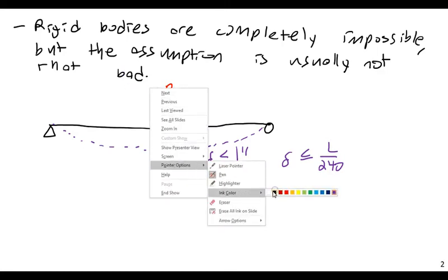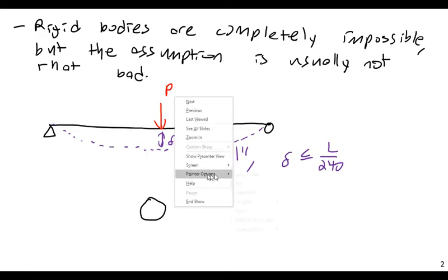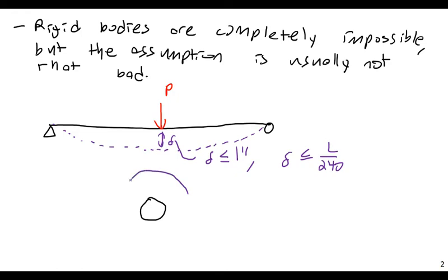It happens with moving systems. So for example, if I have a rotating shaft, a drive shaft that is rotating, the stresses within this, as you learn in mechanics of materials, are going to be determined by the polar moment of inertia, which will be proportional to the radius to the fourth power.